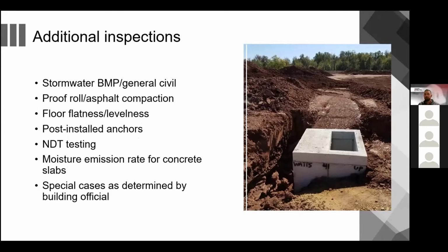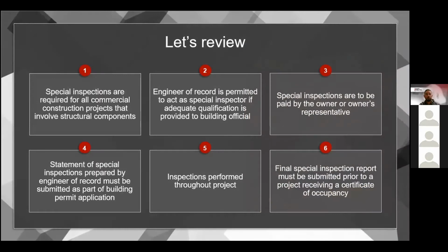if we have a building that we're building on, or maybe making an addition or putting a mezzanine in, we want to test the in situ concrete and make sure that it's up to strength based on the design. And as well, there are always special cases, as determined by the building officials, that they might want a higher level of inspection on. A quick review here for everybody.